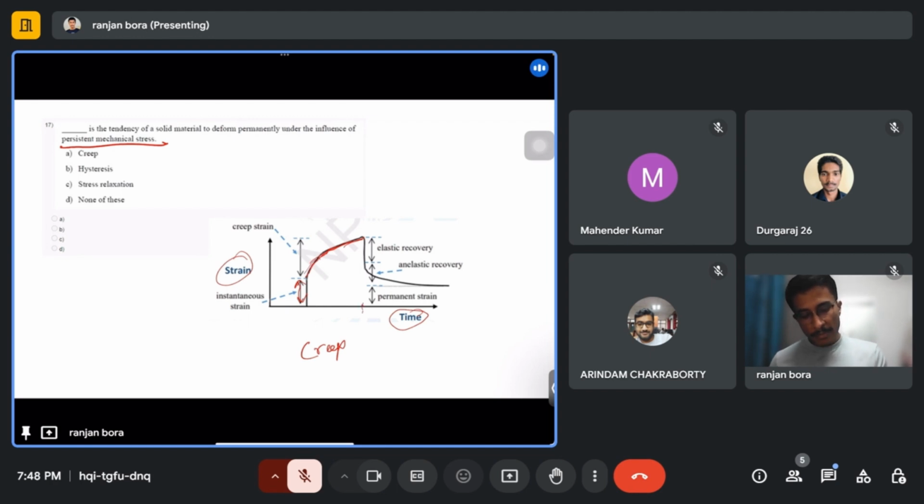And after a certain time there is some elastic recovery in the material, meaning some of the strain we applied will get recovered, which is instantaneous, an elastic recovery, and there is some inelastic recovery, that means strain will recover after a certain amount of time, it will not be instantaneous, and after the recovery some strain remains in the material permanently.